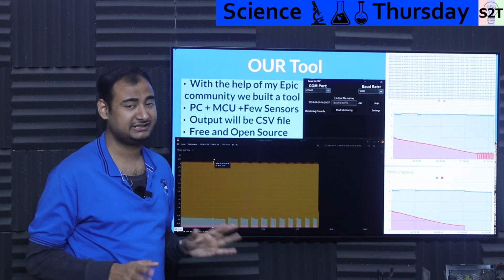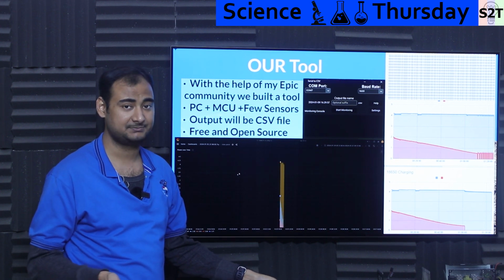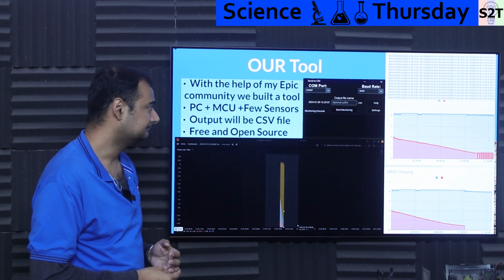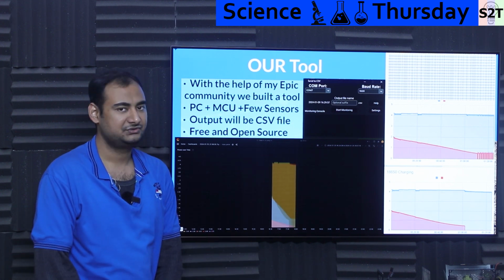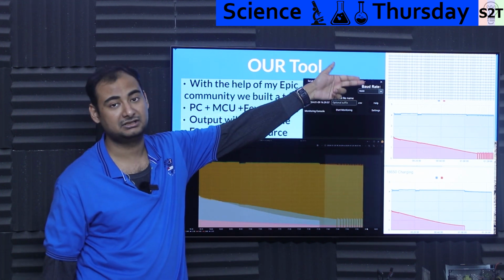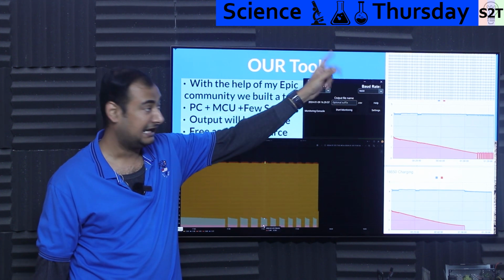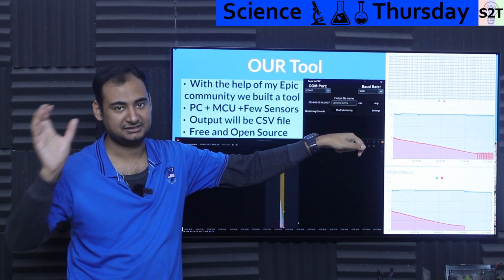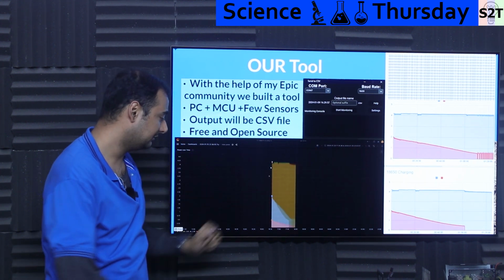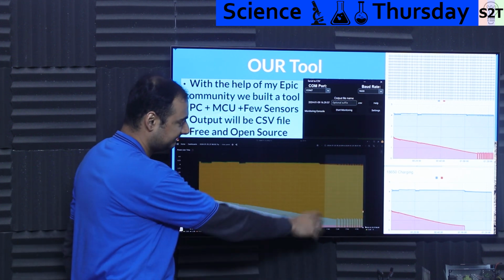You're going to get at least 25 Hertz. I'm getting that with this system. I'm pretty sure if you do it with a proper ESP32, you're going to get more than that. But you can get that, and then you can go YOLO on it as much as you want. In this scenario, I've even built in date and time, but it's using the computer's date and time. So computer date and time and elapsed time are also there. That's why you can get the graph of the first minute of charging, 10 minutes, 30 minutes of charging. Or if you put it in Grafana, it requires date and time. So date and time is there. Now you can zoom in.